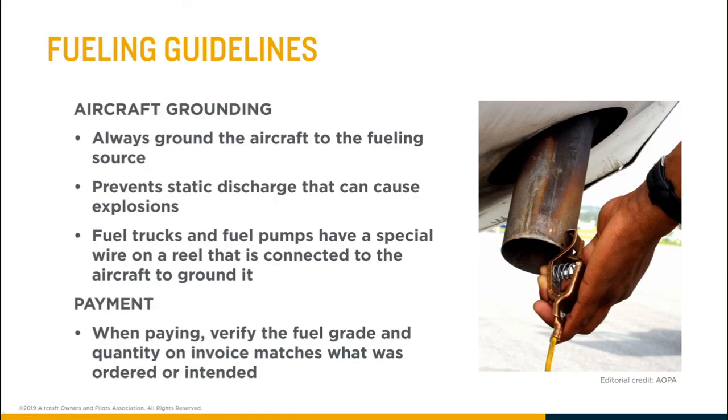If you had a bunch of charges built up on the metal part of the plane and you get a little spark while you're fueling the plane, then that's going to cause those things to catch on fire, and that's a problem. So you want to avoid that. So you always ground your plane while fueling.